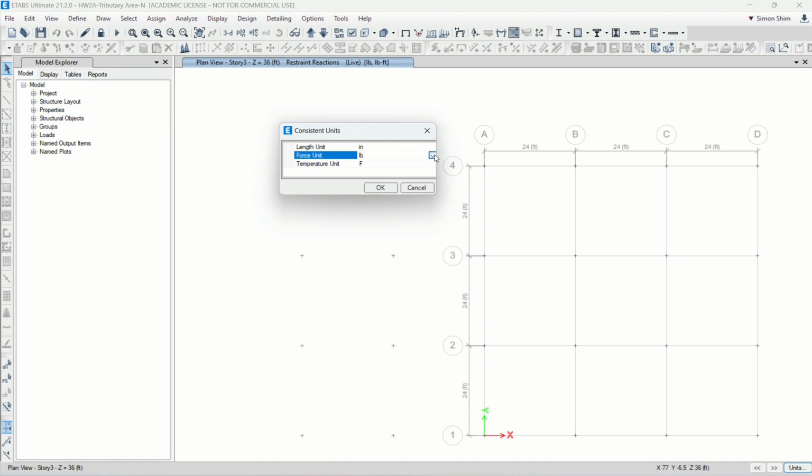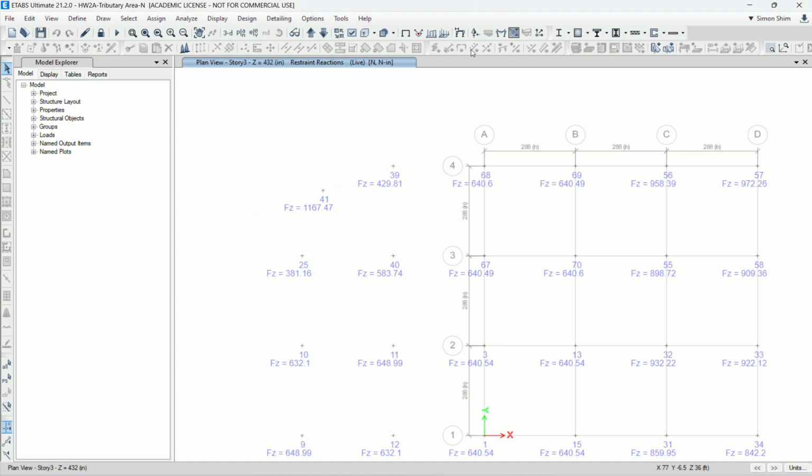You may want to change to kilonewton, Newton. Even after we finish the whole thing. See, this is only the output mode, but internally everything is done with imperial. If you want to print out some output, you need to change the unit. So here, this is Newton. But don't mix it, because you're going to make a lot of mistakes.